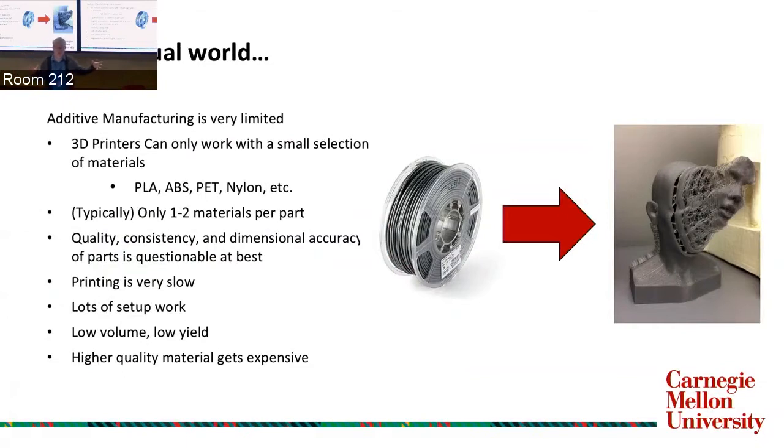And then the number of materials we can print with consecutively in a print is also limited. That machine can do one. Bob's got a machine that can do two. There are FDM printers, we'll talk about what that means in a second, that can do up to 4, kind of where it tends to top out. And there are other printing methods that can start to get into that multi-material land, and we'll talk about that in the end. We have lots of limitations.